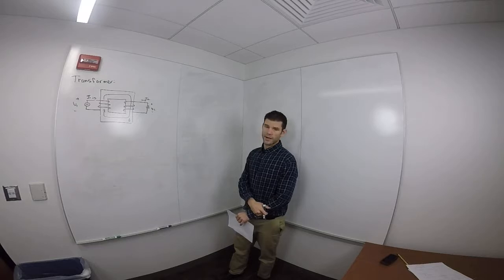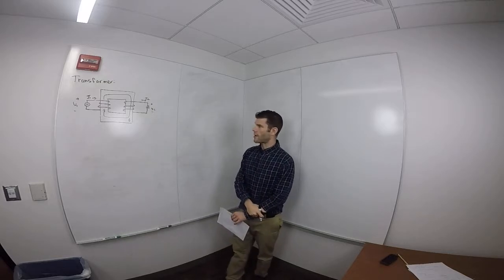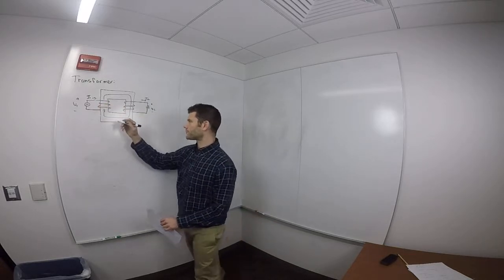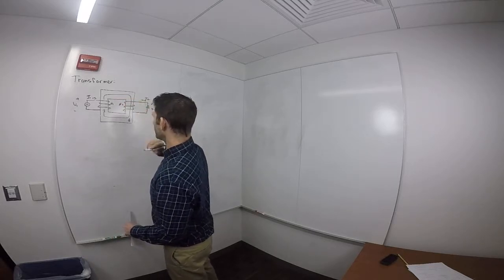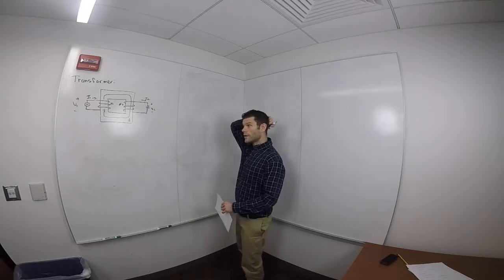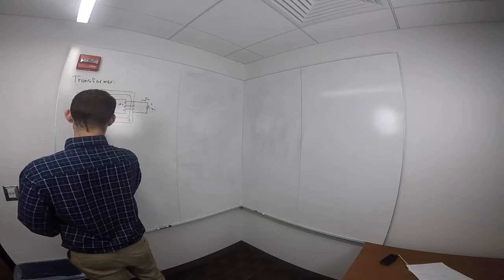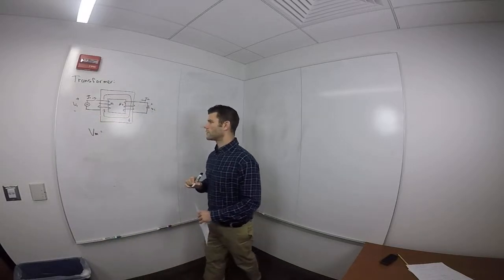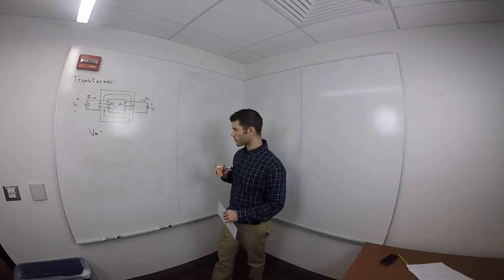Okay. So what we should notice here is that we have basically a magnetic circuit, okay? If we have a current which is going to flow here, which I'm going to tell you is going to happen because of the principal operation of a transformer, and we have a current that flows here, we're going to produce two MMFs. Let's say that we have N1 turns in that solenoid and N2 turns in that solenoid. We can then develop an equation that would say the total MMF is going to be basically the difference of the two, right? The difference of the two.